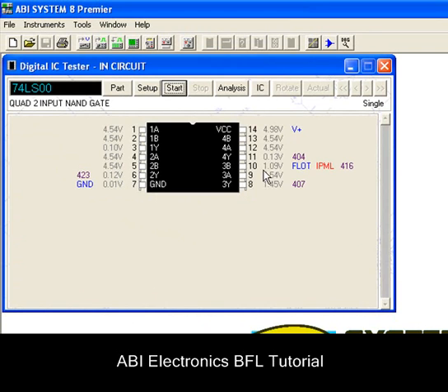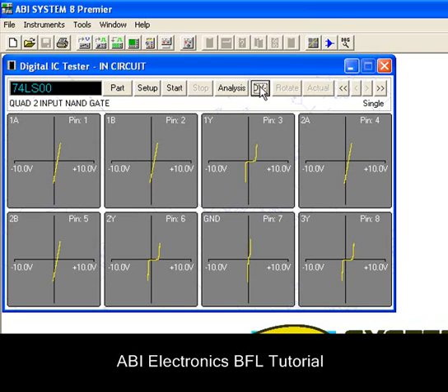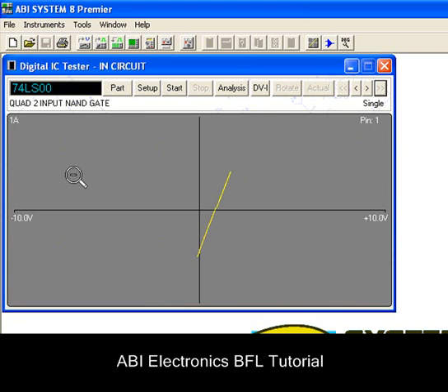The voltage results are displayed in grey, the connections in blue, the logic conditions are displayed in red, whilst the thermal results are in purple. For VI results, toggle the view to get the analog signature of each pin of the device. A zoom-in function is also available.